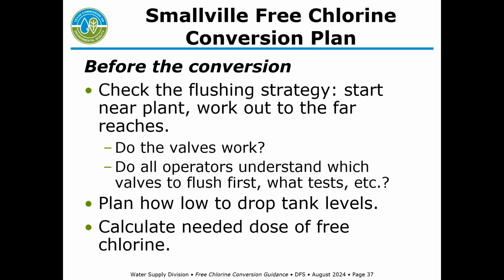So before the conversion, you're going to check your flushing strategy, start near the plant, work out to the far reaches, make sure everything's working. Does everybody understand what they need to do? Plan about how you're going to, how low to drop your tank levels. I mean, the more you can drop them, the easier it is.